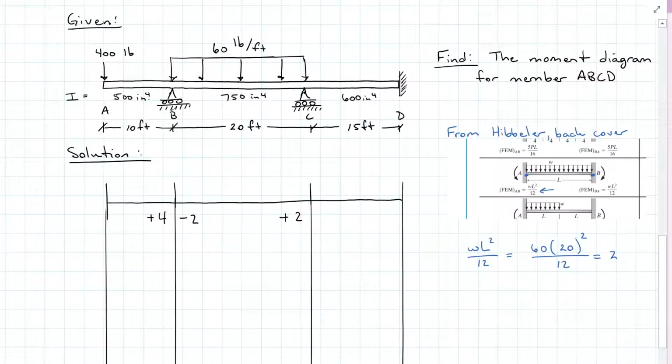I do not have any load between C and D, so my fixed end moments are going to start 0 there because I do have connectors. No connector at A, no moment at all. Connectors at C and D with no load, so my moment starts at 0. So there's my fixed end moments for step 1 of solving moment distribution method.